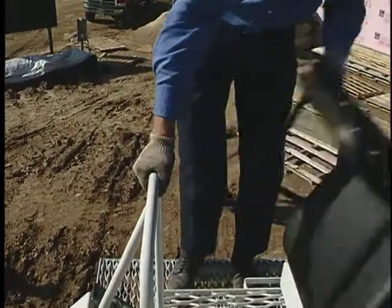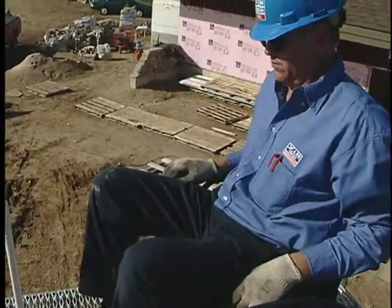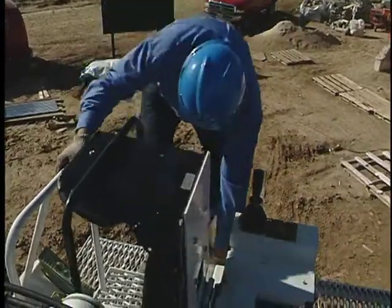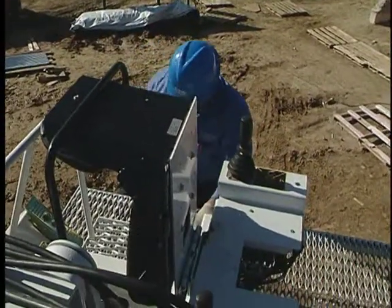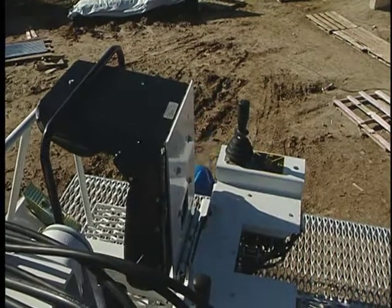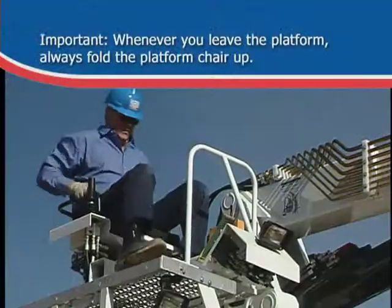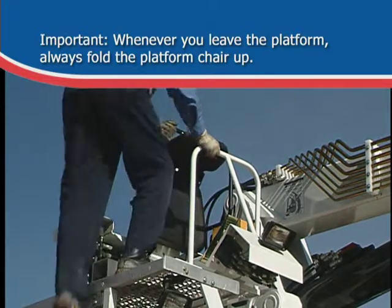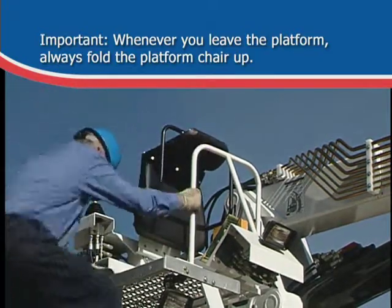Once on the platform, unfold the operator's seat. The folded seat is in effect a safety switch. On some models, whenever the seat is folded, the platform controls are disabled. Remember, when you leave the platform, always fold the seat over. Make it a habit for your safety and the safety of others.